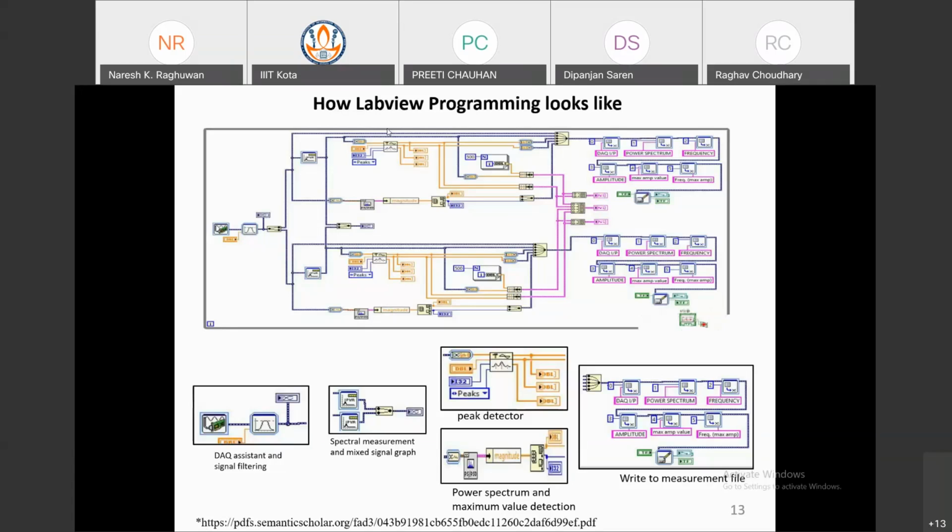After that, how to measure the fault. So some amplitude or frequency domain and multiple graphs you can plot here. So this is not a hit and trial method, but use it properly depending on what you need. Okay, capturing of the signal is okay. After capturing the signals, what type of display of the results you are going to have, accordingly your LabVIEW programming you will write. Some filter is also required. Suppose you are denoising, some filter you can put in the programming. Okay, so this is the overview.